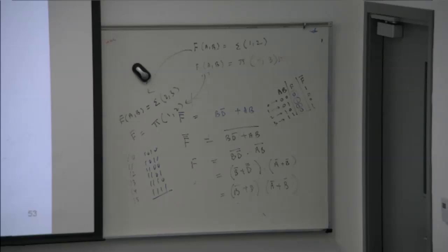So now this is example number 1. Fill in the ones. Can you see here? These are all prime implicants. Do we need them all? Which are redundant? No, not the blue one. The pink one. Now, can you see the pink one is also redundant? This one is also redundant because it is covered by the pink one and also the blue one. And this one is covered by this one and this one. So these are all redundant.